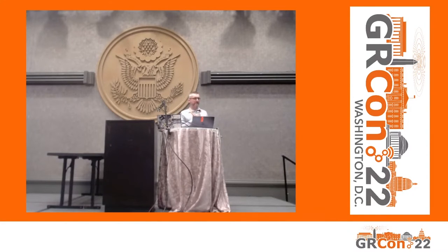Thanks for the presentation, very good. I have some experience with the GPIOs, and maybe it's more of a comment or question. You can use the ATR feature, but is there a way to configure the GPIO transition to happen slightly before or slightly after the radio switches state? The way I've been doing it is I use the timed command, but then it's a little bit more work. You can't just trust the radio to do it in hardware. You have to do it in software.